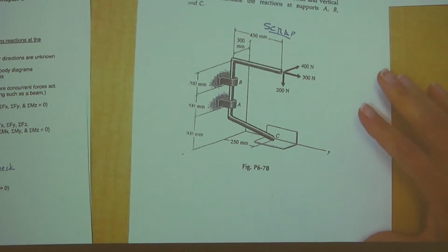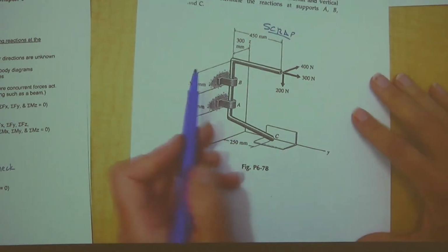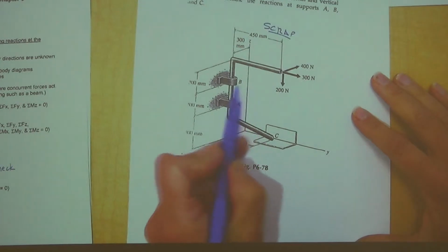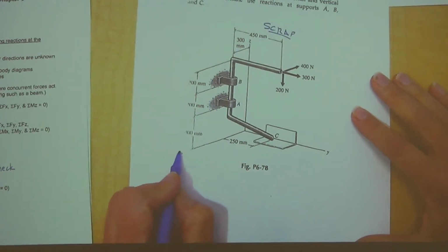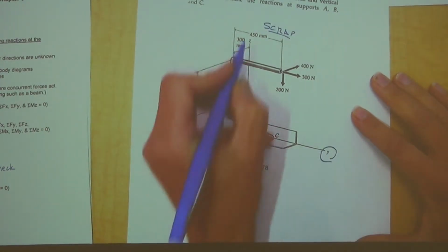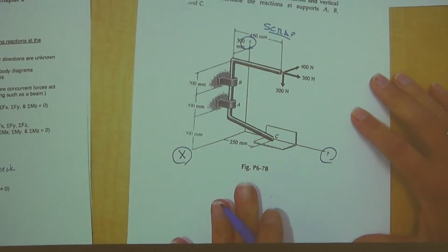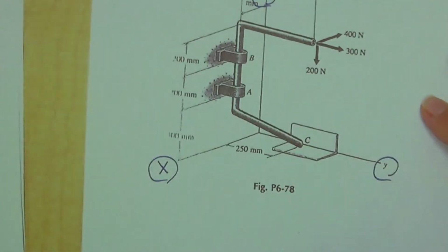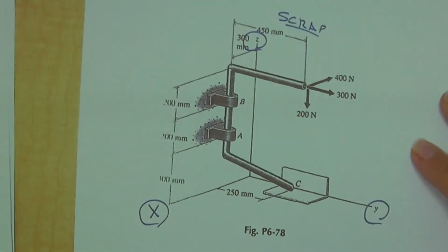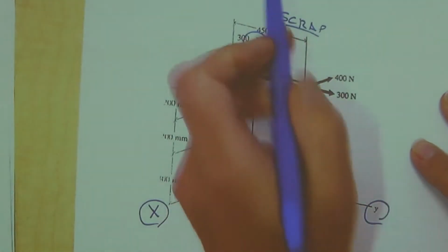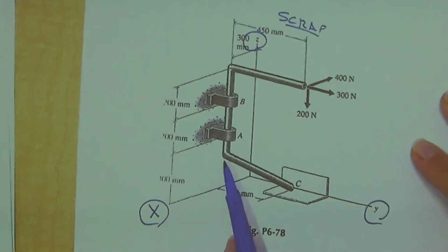So let's go around. Radian, let's start with you. So which forces are on B and A? Notice where our axes are. There's X, Y, and Z. Remember, on a 3D problem, always find out where our axes are. So what can it resist? It's resisting force reactions. Is it X, Y, or Z? Or let's do the opposite. Which way can it move? X, Y, or Z?